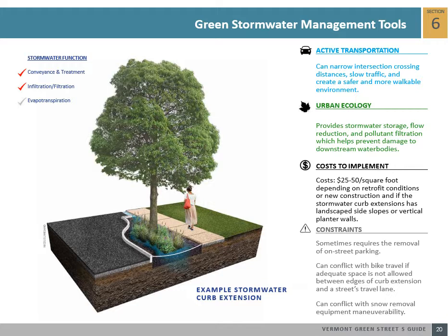Reinforced grass and gravel grid systems also allow rainwater to soak into open pore spaces in the soil while providing a rigid driving surface for travel and vehicle parking. In areas needed for intermittent load-bearing use, such as overflow parking, grass paving or other paving planting hybrids can be used to provide structural support while allowing plant growth and stormwater infiltration.